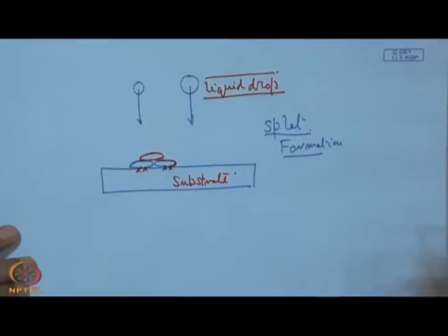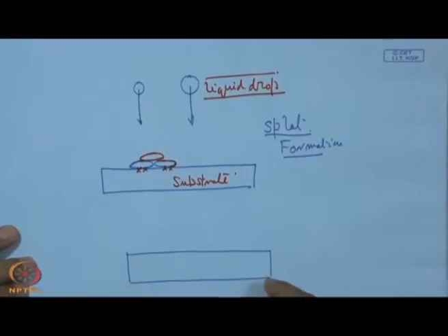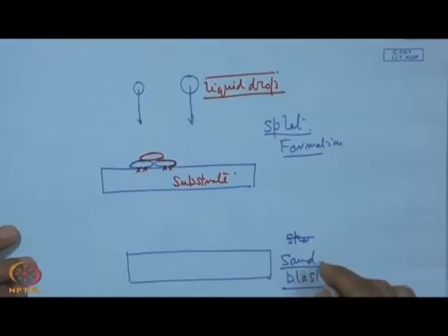So, the surface needs to be properly prepared, that means degreasing, pickling, and also mechanically roughening the surface. That means, here we need sandblasting, and for this sandblasting, as usual, we need to control the grit size, stream velocity, and also the angle of incidence and standardization of the roughness of the surface.